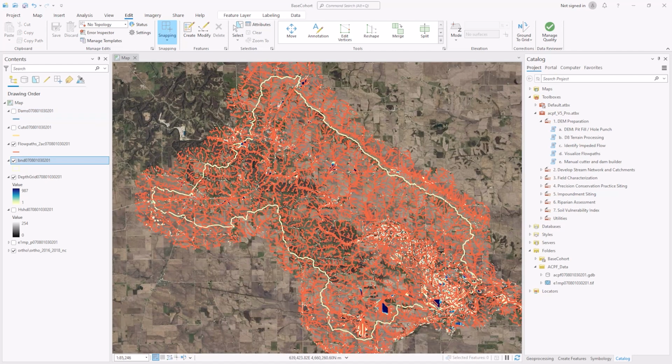I'm going to touch on a couple of resources that may assist in producing your cuts. There is a possibility that your local GIS group or state agency, such as your Department of Transportation, may have a culverts line layer available. This would be a good start to your cuts layer, and there are a couple things to note. You will want to continue to pan through your watershed as verification is likely needed on these lines. Not necessarily for their location, but for their length. Remember that our cuts need to completely cross our impediments, and there is a possibility that the provided layer does not.